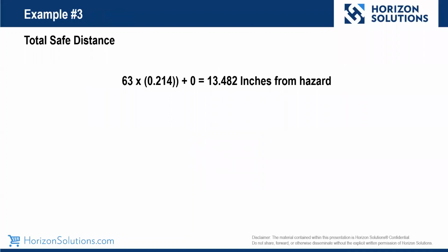When we add all of these up, our reaction times of 60, 104, and 50 milliseconds, we get 214 milliseconds or 0.214 seconds and a total of 13 and almost a half inches. So slightly closer than our previous system, but still much farther than the relay-only system.